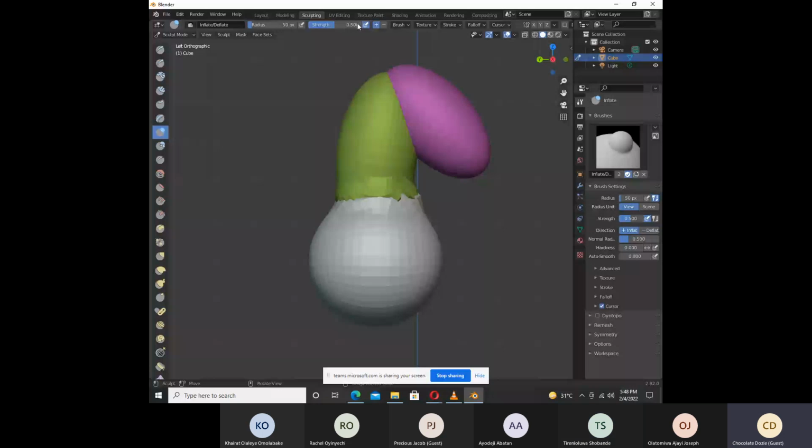Make sure your inflate direction is positive. It should be positive the moment you select it. So if you have all these three checked and you come to the particular point where these shapes or objects meet, then hold click, and keep rubbing on that spot. All right, like you're massaging it, it's going to inflate.